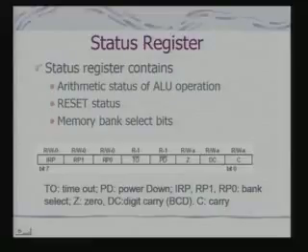See, what we have is that when an operation takes place, the result which goes out from the ALU has to be stored in some register. Which register it is to be stored in depends on the D bit. There is one particular bit in the instruction word which is called the destination bit. Depending on the value of that bit, if it is 0, then that data is stored in the W. If it is 1, it goes to one of the general purpose registers.